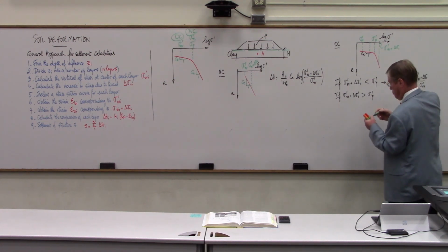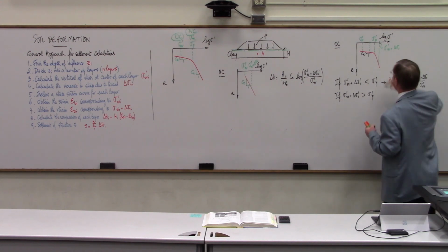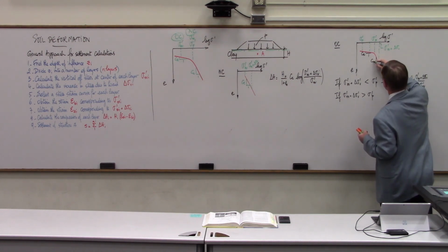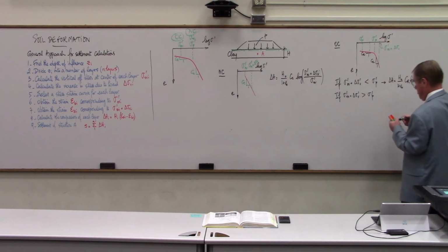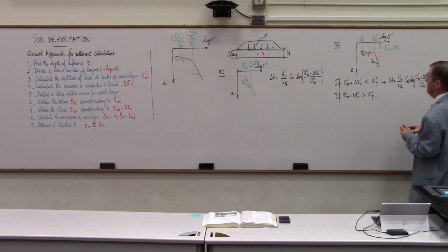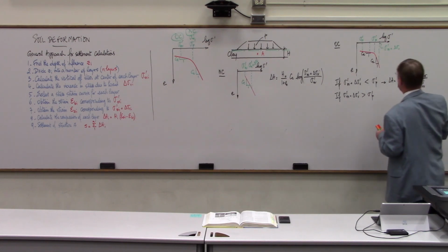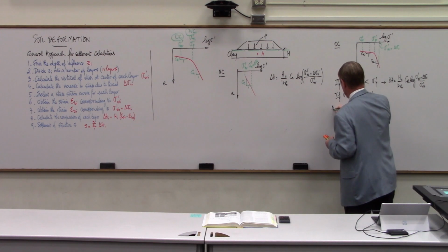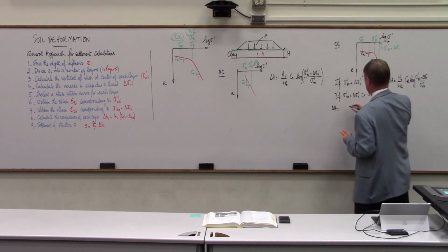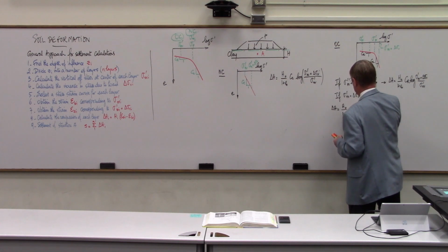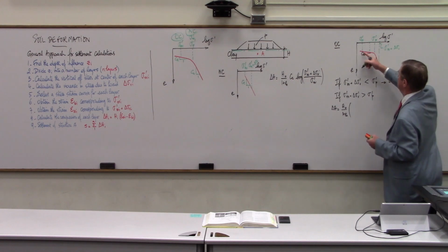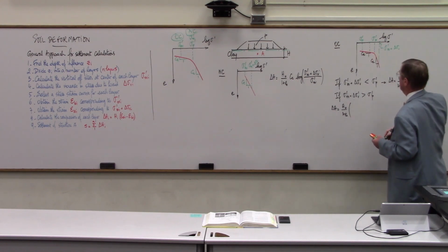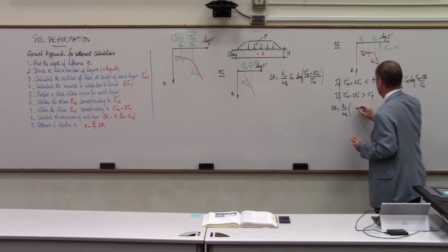So in this case, we've got to do two parts for the calculation. And this is C sub C. So we're going to do one part from sigma prime OV to sigma prime P, and then one part from sigma prime P to sigma prime OV plus delta sigma. Okay? So the equation in this case is going to be delta H equal H0 over 1 plus E0. That part is common. But then I got to do the first part of the compression up to sigma prime P. So I'm going to write, and the slope is C sub R.